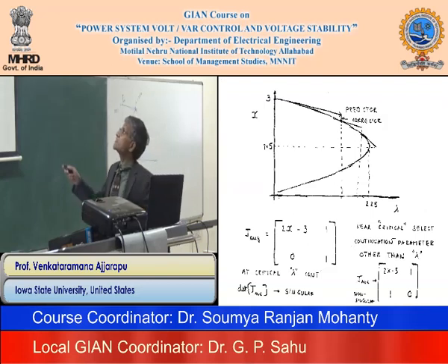Another advantage is I can continue on the bottom part of the curve, because I can get the bottom part of the curve also. Whereas most of the power flow programs, if you see, only do the upper part. That's okay, because most of the time you use only the upper part, right? You don't need the bottom part. But as I mentioned before, in one of the examples you tried, some of the bottom parts may also be stable, or you can operate there. It is non-linear load. So in that case, you need the bottom part also. You don't need to stop there. You can get the bottom part.